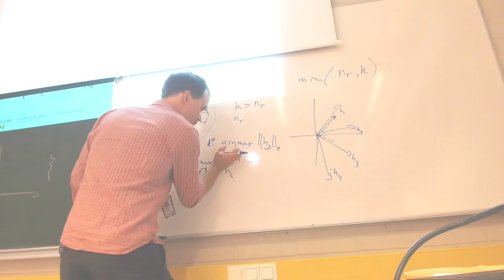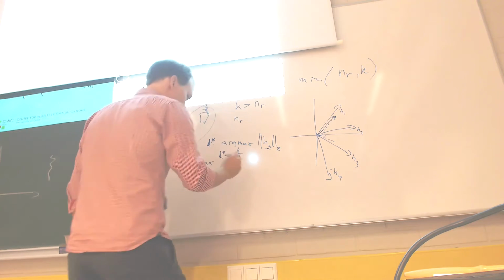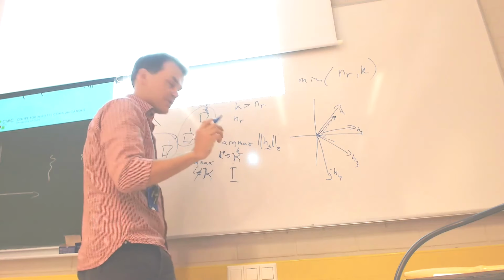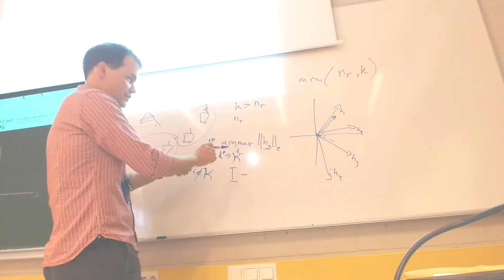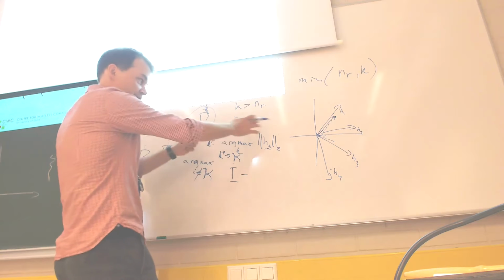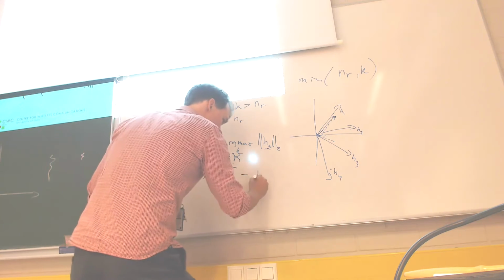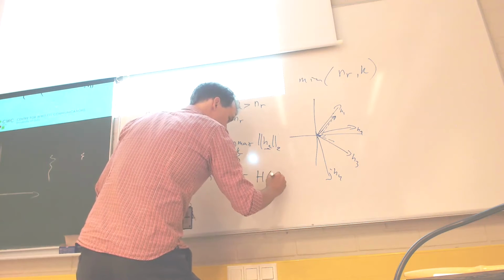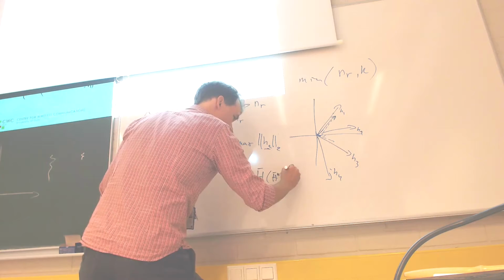There are 2 ways. Basically, you can compute the projection vector, or we remember from wireless communication 2 that the projection matrix onto the null space of all users that belong to that already selected set of users is I minus H-bar Hermitian H-bar.